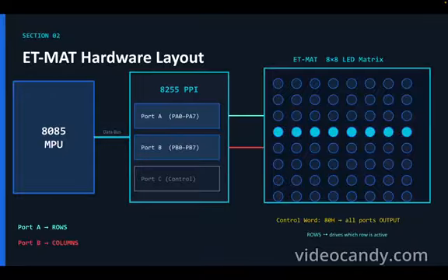How it works is that our 8255 has 3 ports, port A, port B, port C. Here port A controls the 8 rows, port B controls the 8 columns, and port C is the mode configuration for my register. So using port A we are setting the logic for our 8 rows, and using port B we set the logic for our 8 columns.